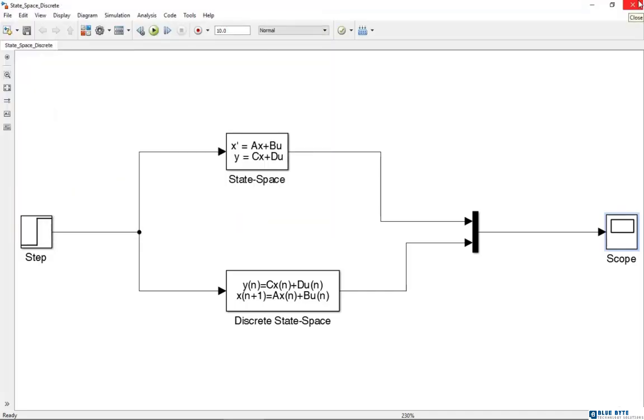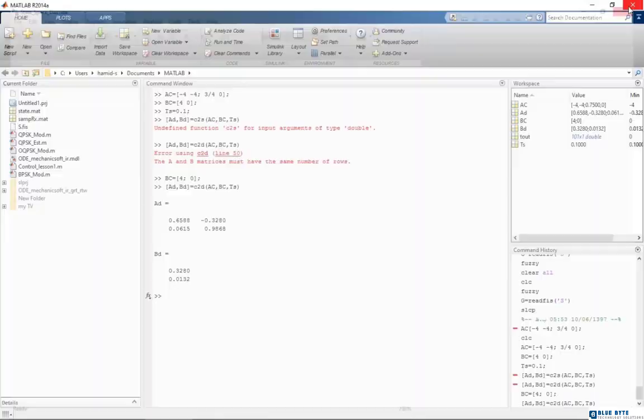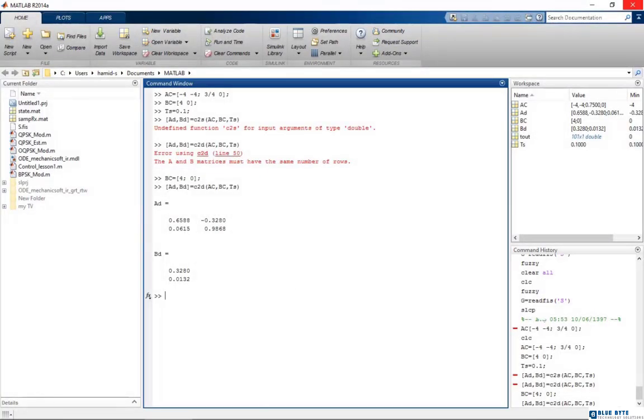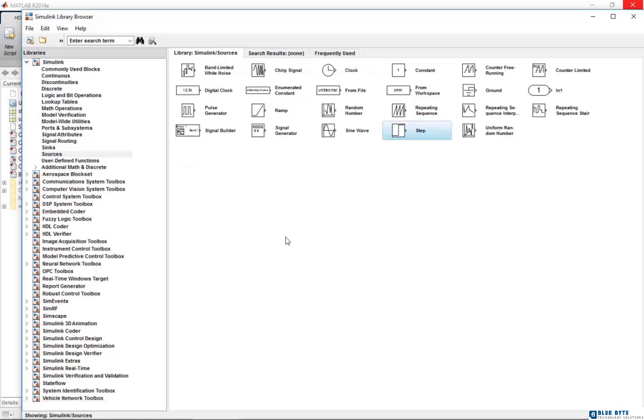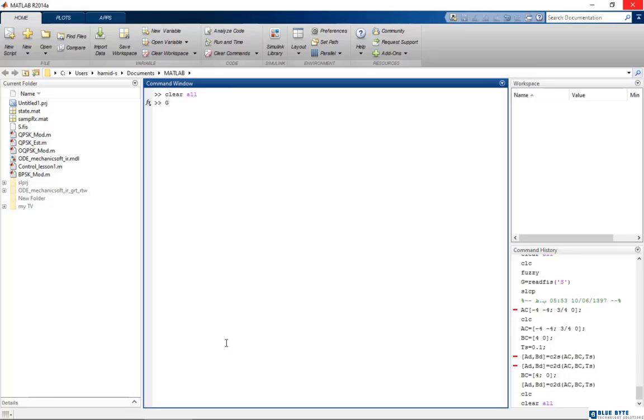Let's work on another example. It's similar to what we had in simulation of multiple continuous systems. Here I want to show that kind of simulation in discrete systems. Also, I want to show a hybrid system in this example. First, I simulate the system in continuous form using the ZPK instruction, which is related to zero pole. We have 2 poles in -2, 1 pole in -3, 1 pole in -10, and also the gain is 2.